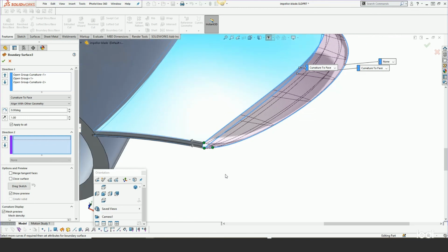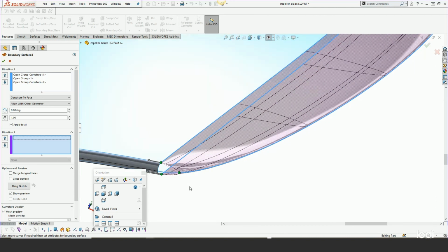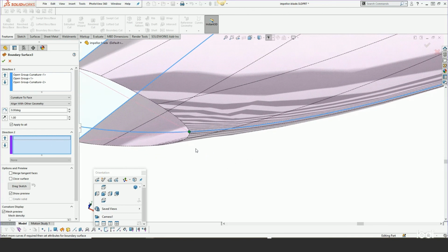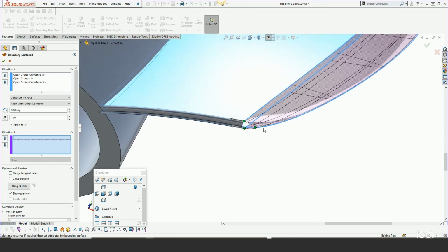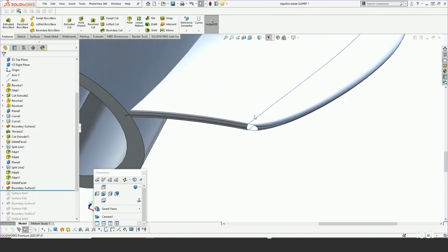And actually this is a better way to get better matching across this boundary, because as I mentioned before, if you don't have second direction curves, you're just going to get better matching on the first direction because there's nothing delimiting it or holding it back from matching. But in this particular solution, this becomes rather tight down here, and I do want to actually define these boundaries here. So let's edit out of it and look at our solution.